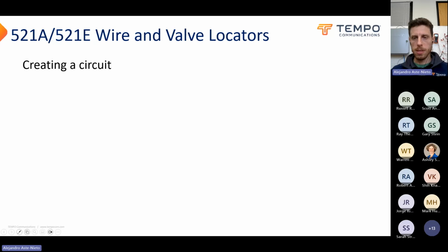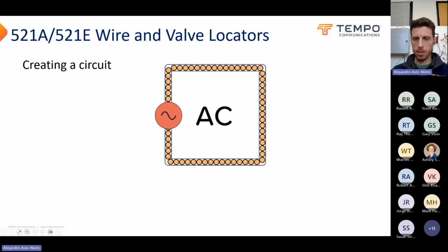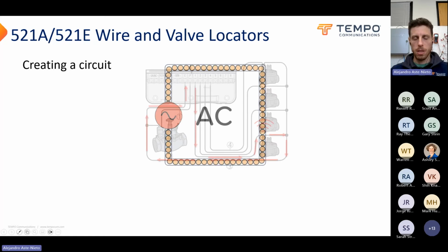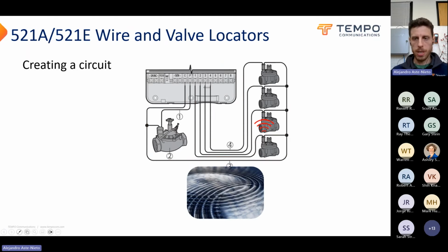And the AC from the transmitter requires that we make a circuit, signal leaving from the red lead, going out into your field wiring, and then returning onto the black lead. The simplest way to close that circuit is to connect with the valve wire and common wire. But like I mentioned, because they're laid right next to each other, the signal going and coming is going to cancel. Those right-hand rules, if you look at things clockwise one way and then clockwise the other way, they're going opposite directions.